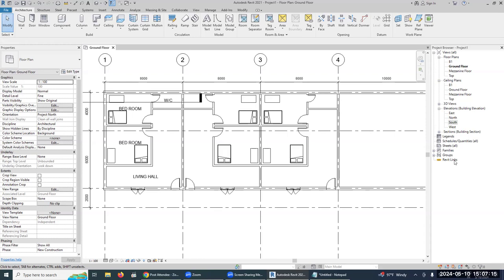Again, take mirror. You lose the selection. Again, you have to reselect it. Okay. If you miss your selection, again you have to reselect it. Then hold the shift key to remove the internal walls. Now okay. Then again Mirror. Keep the last one. You didn't do this one. There was a continuity of the wall here.